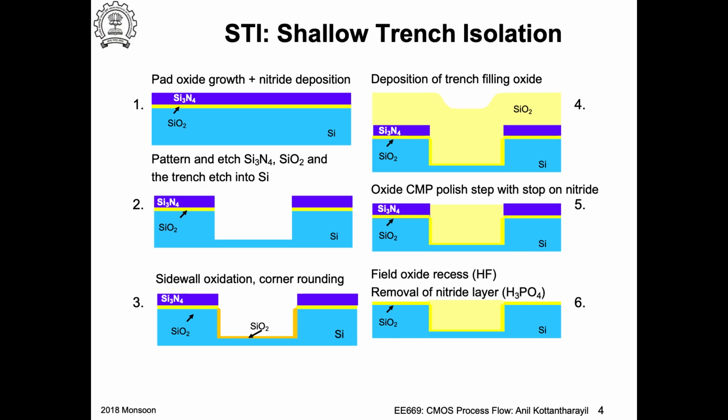So this has to be about 550 nanometers, okay, and this is a high density plasma oxide, typically an inductively coupled plasma CVD process. So this would fill the trench by a deposition and etch process, right? So that you fill the trench without any gaps.